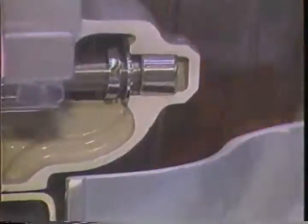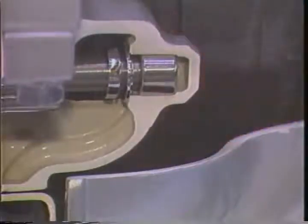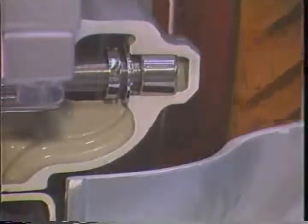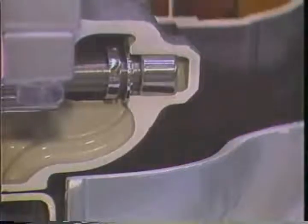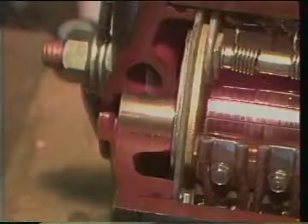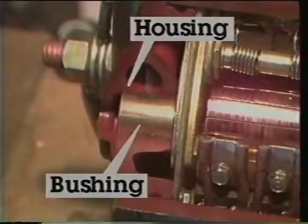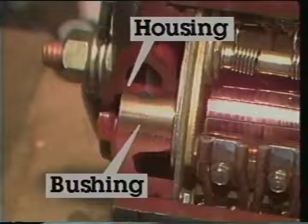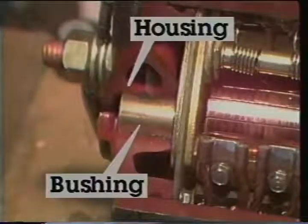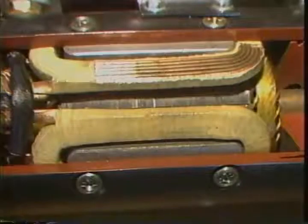This cutaway of the drive end frame shows the shaft bushings, thrust washer, and C-clip washer in chrome. The flywheel ring gear and transmission torque converter are rotating behind the starter. Starter bushings are usually made of a soft brass-bronze alloy to reduce shaft wear. The bushings can be removed and replaced in their housing during a rebuild.